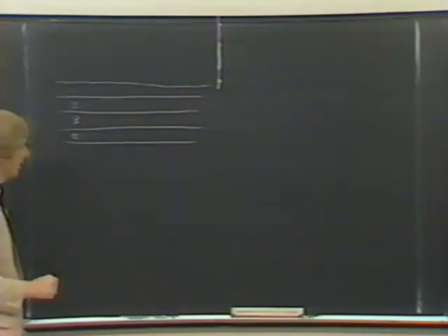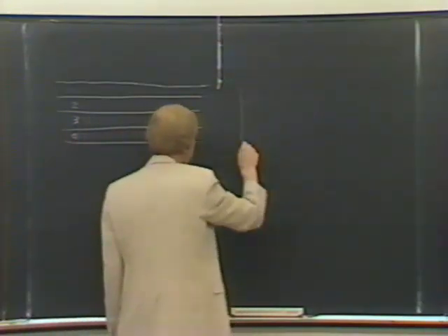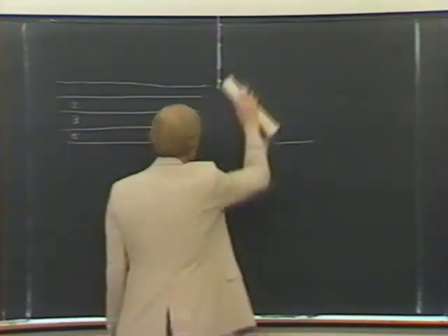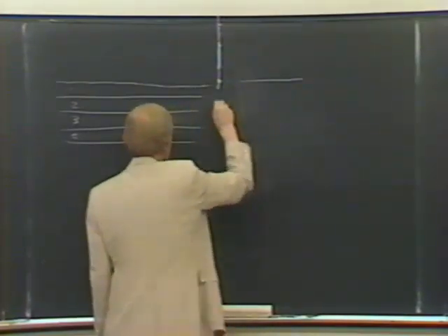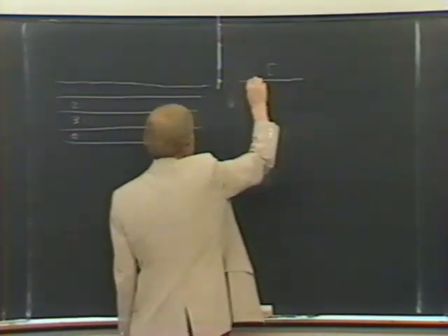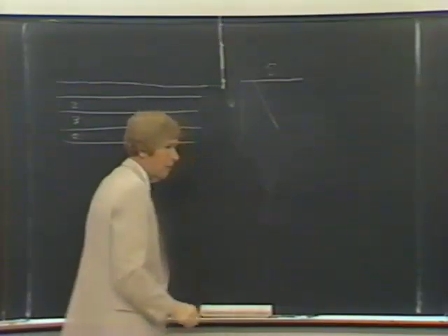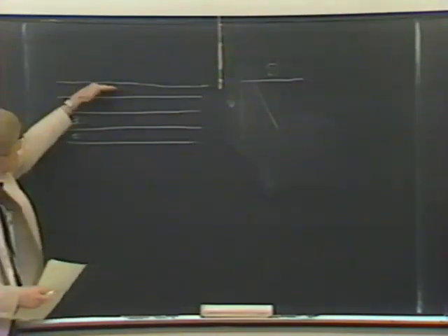And what we assume typically is that the shear strength, I'll call this depth, I guess I better draw it differently. Depth here down into the bed, and shear strength, that it increases from whatever the value is for a new deposit linearly. And the rationale for that is those plots that you saw in your syllabus, showing that near the surface anyway it's linear, or nearly linear. It may break. Remember, we had some that had breaks in them.